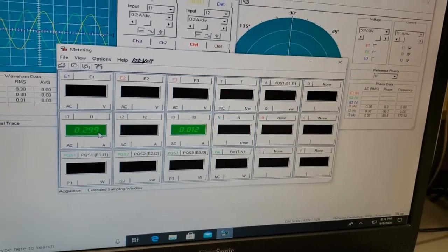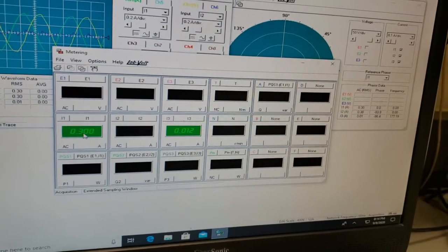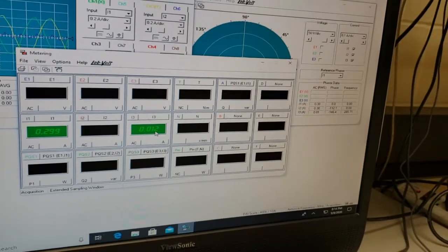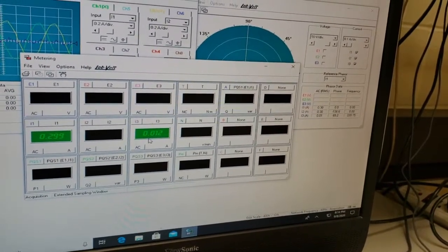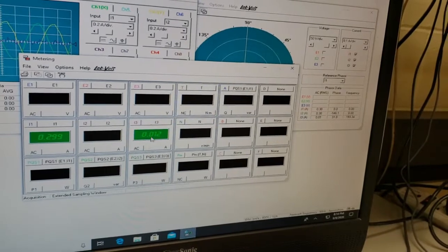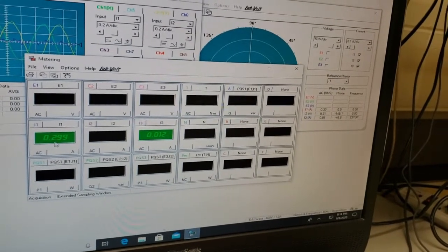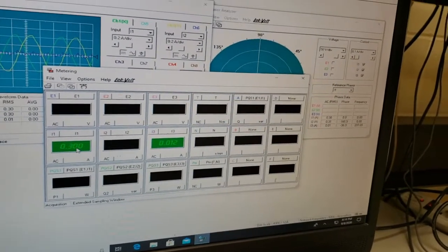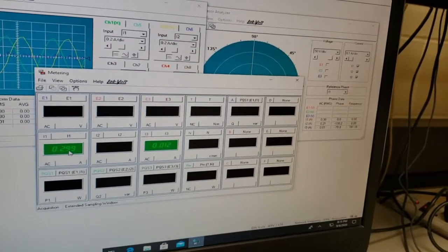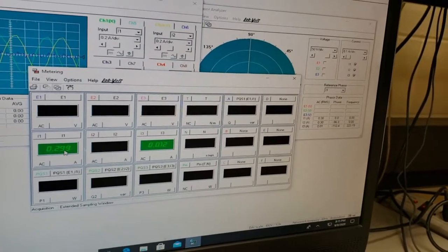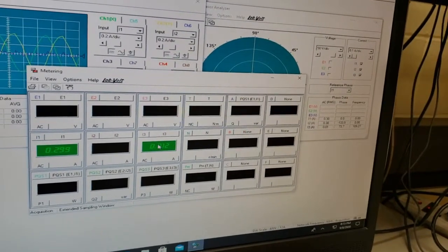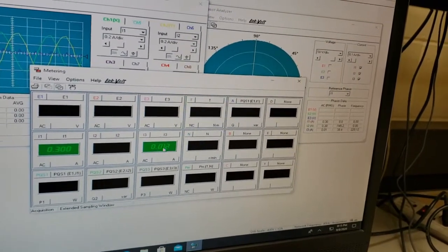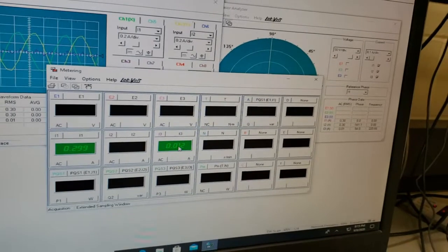Observe, we have 300 milliamps through any of the loads, RMS obviously, and we have about 12 milliamps in comparison going through the neutral line. So it should ideally be 0, but you can see that it's very close to 0, especially when compared to the actual currents moving through the loads. And that's what you have when you have a balanced load. That neutral line, because it has so little current, it can be made much thinner, or it has less strict requirements on it because it doesn't have to carry as much current, assuming that the load is balanced.